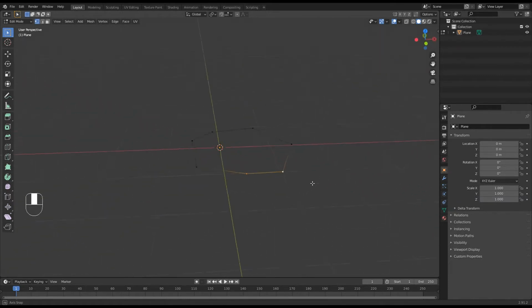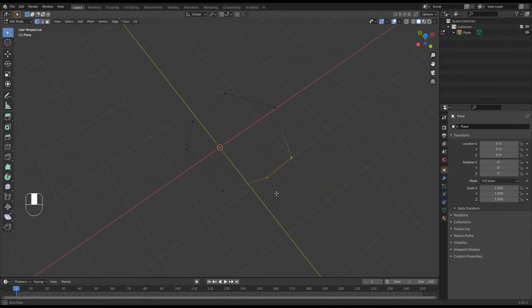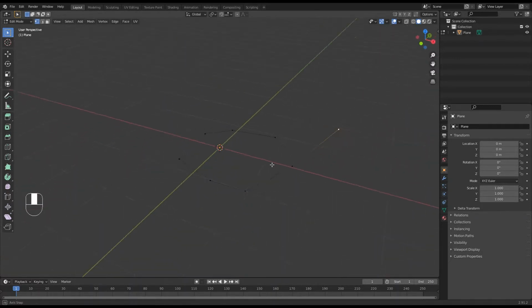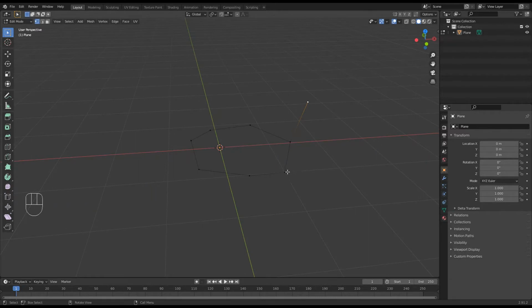Right, so I've now basically drawn the profile of the base of my bowl. Now I want to start drawing lines upwards into 3D. Now, if I select that and try to draw up, I could do the Control right click thing again. So there's the Control right click, and it's drawn a line up into space. But this line is drawn at the angle of the screen. So if I navigate with my middle mouse button, you can see that it's really angled back because that's the angle that this plane was in relation to the screen.